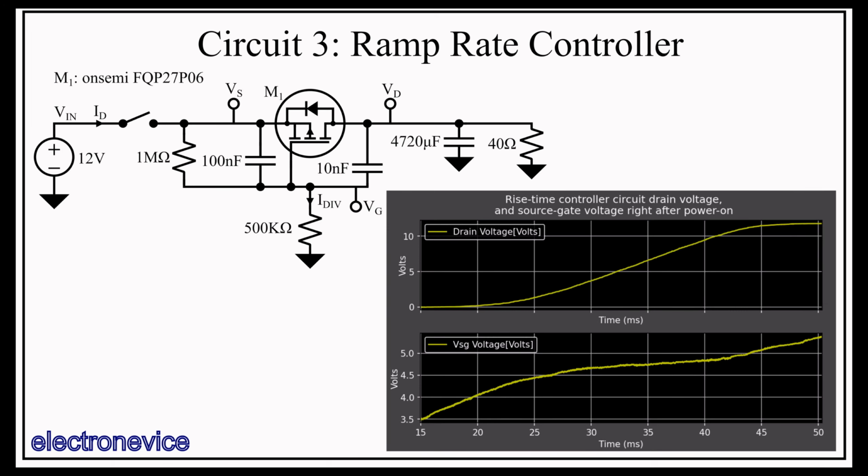As a result, getting an accurate turn-on rate from the analysis from this kind of circuit requires a great deal more detailed analysis to produce. As detailed analysis tends to be time-consuming and testing this kind of circuit is generally pretty easy to do, it is simpler to do a rough design, then test the circuit and tweak the values as necessary to get the result you want. Rarely do you need a soft start circuit that must turn on with a very specific turn-on rate and time constraining you. You can typically just design the inrush to be lower than specified, then make sure with testing that component deviations and non-idealities in your assumptions don't cause it to be too high.